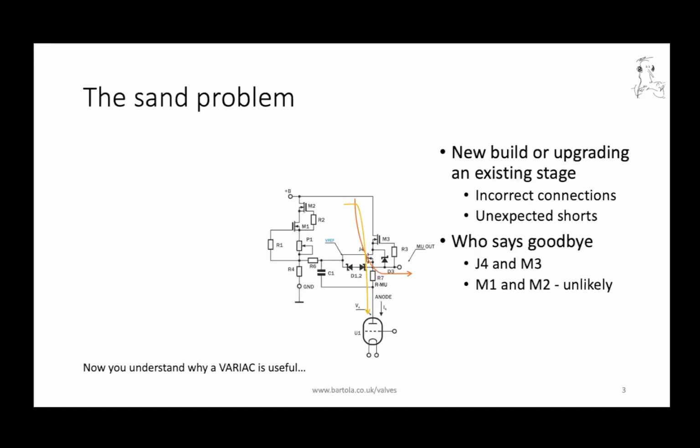That current can be modified using the trim pot P1, and therefore you can define a range of the reference voltage to be set. And fundamentally what it does is set the operating voltage of the valve. It's not the current, just the voltage, the anode voltage.